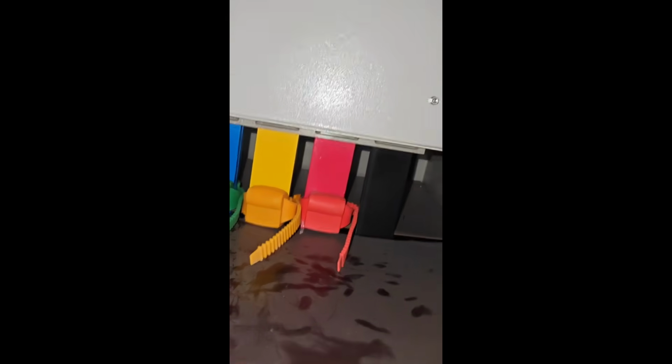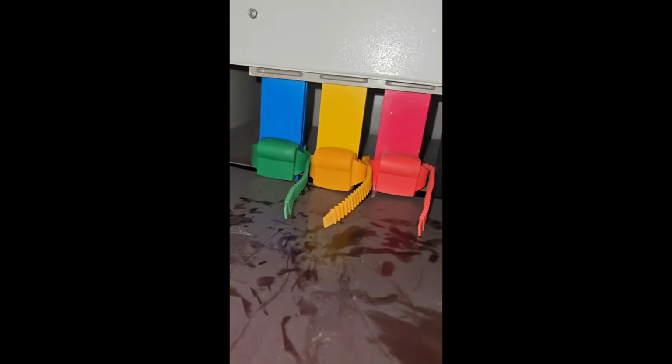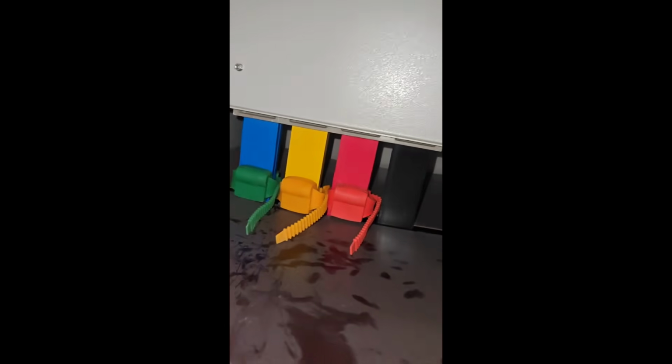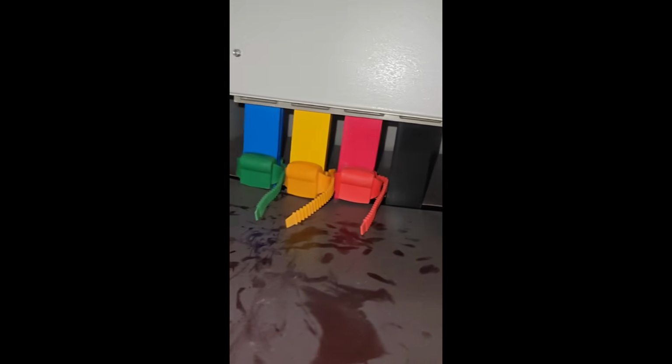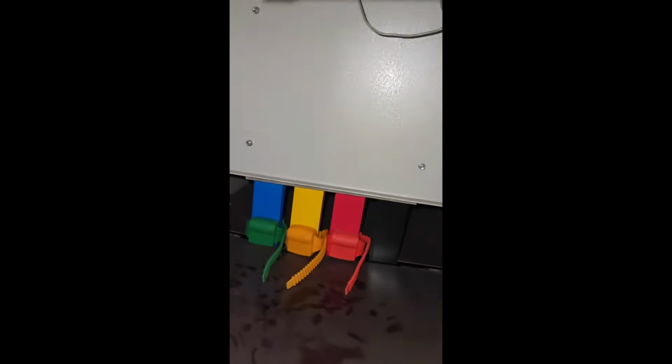And what you see over here are temperature sensors which are attached to a bus bar for monitoring. Now what we are doing is monitoring the temperature of this bus bar, and these sensors are wireless. They communicate with a hub module using wireless communication based on 2.4 gigahertz.